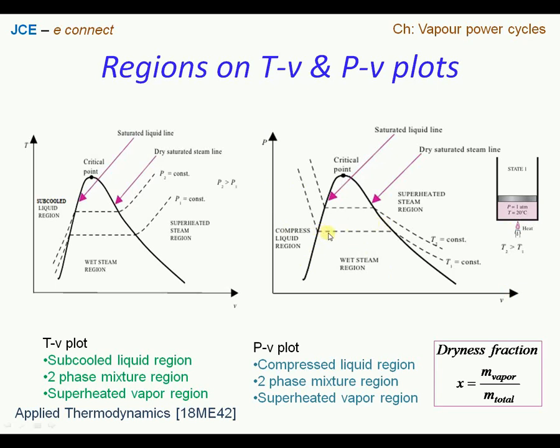But as the process continues, slowly the steam formation takes place because the latent heat of vaporization is getting added, and it is converting the liquid to vapor. When the system reaches the midpoint, we have quality at 50%. That means among the total mass of fluid, 50% of the liquid has been converted into vapor. And as it approaches the end point, the saturated vapor point, which is called dry saturated, all the liquid is now converted into vapor. Therefore it is called the dry saturated vapor point. So these are some basics for us.